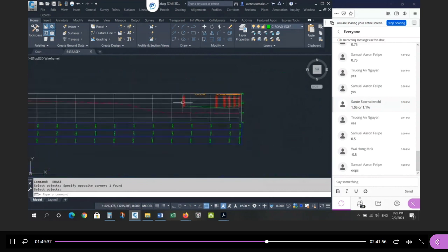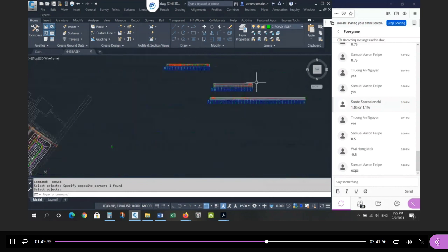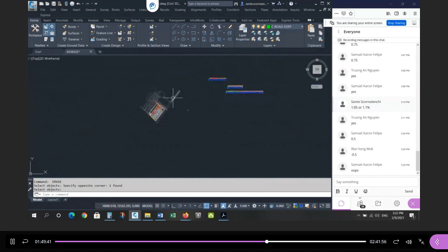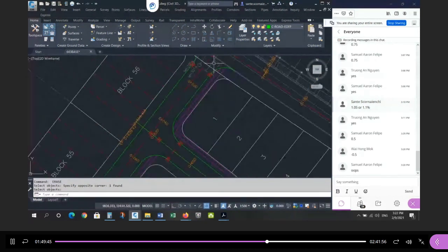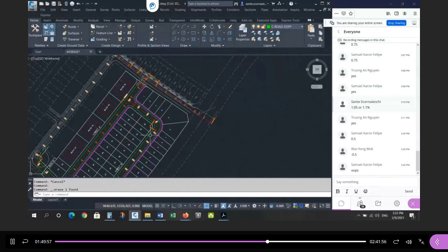Now I'd like to take that elevation and bring it to the end of Street B, right? I just designed from here all the way to here. Now I know the proposed elevation for this point here. I'd like to take that and bring it into the profile at the end of Street B. And I'm going to design this going backwards, up chainage instead of forward in chainage, okay?